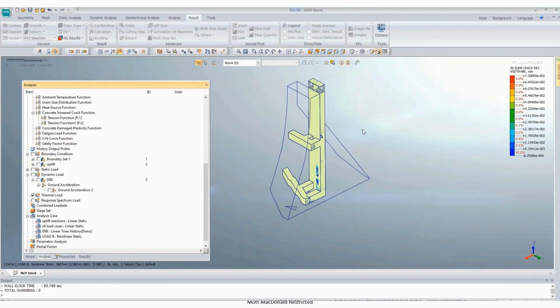I'll show you that the crack width we evaluate manually actually matches this crack width after putting in the reinforcement. We can model the reinforcement here, and then we can perform nonlinear analysis considering some tensile strength, as I have considered 50% of fck by 40. With the same tensile strength, you will find almost the same crack width.